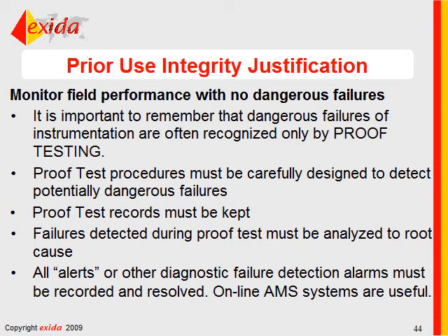And I've seen some pretty lousy proof tests. You know, go out and press the button and see if the bell rings. Well, that may or may not be effective. Proof test records must be kept. It's not good enough to go out and do the test. You have to write down that you did it, and most importantly, if you detect something wrong, you really need to fix it and analyze what happened. And I know that can be painful.